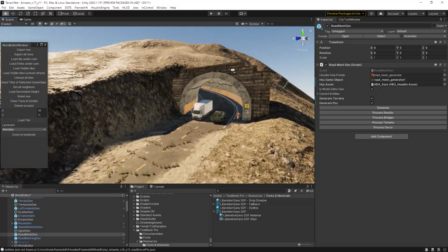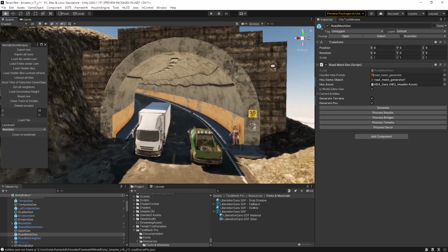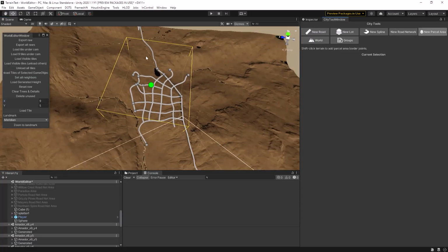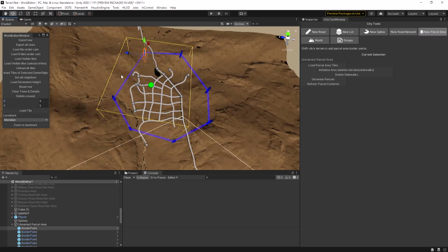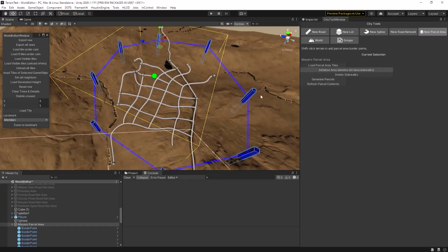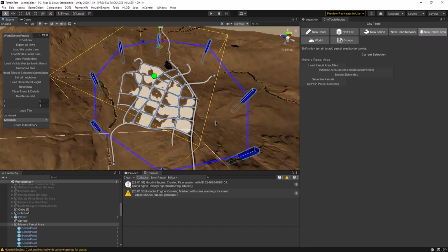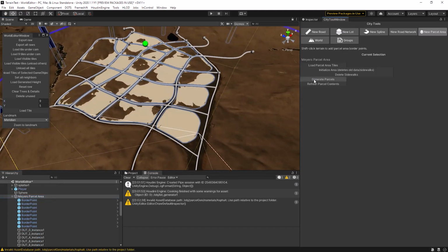We also do all of our terrain grading and blending in Houdini to blend the terrain in with the cities or the roads. And we have a route generator that uses find shortest path to automatically create a road. We have a street network generator that creates the footprint of a city and the city grid layout basically, and then a city block generator which will pack the city block with buildings, and in the space in between it creates parking lots and parks, and it has curbs and sidewalks and all that stuff. And then the building generator just puts in the modular pieces and generates a building of any height,